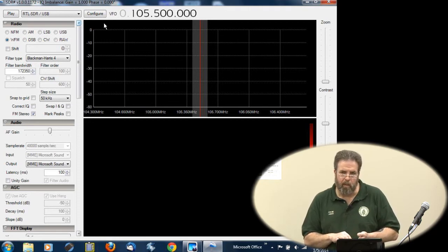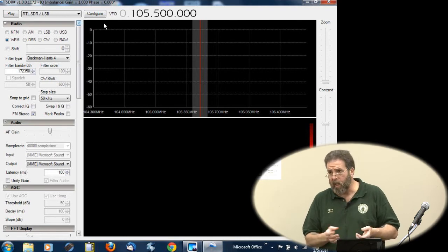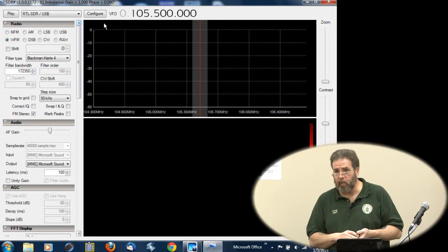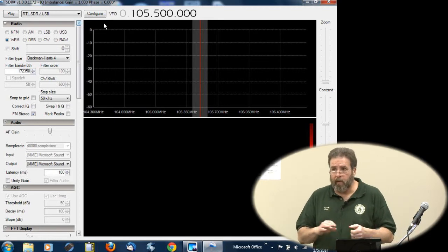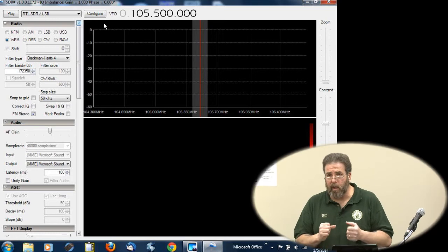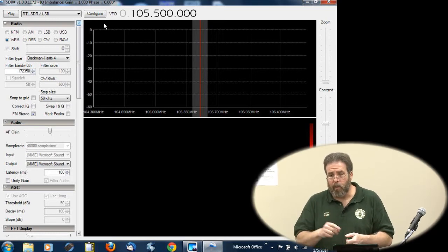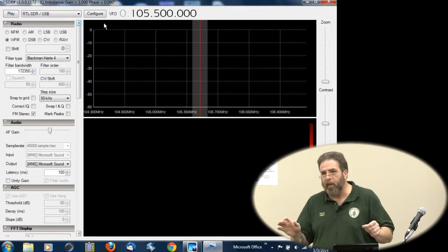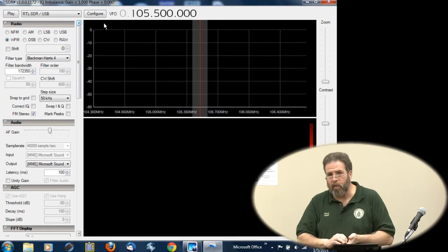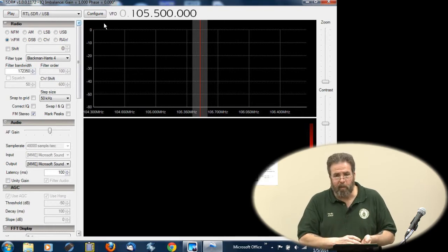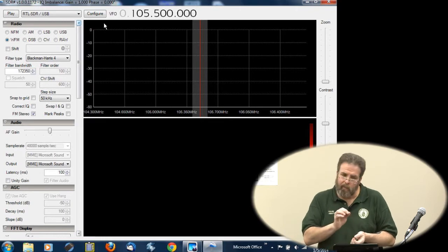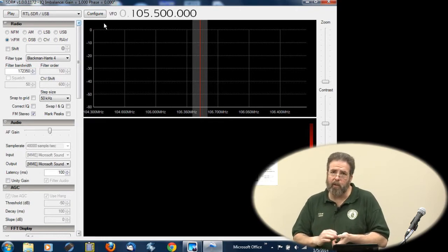I was playing with it a bit yesterday. Like I said, I was listening to guys yesterday. Also, you have to calibrate these. All SDRs have a little bit of calibration you might have to do, and it's really simple. Especially for HF, you just tune in WWV. You let your system warm up for 20 minutes, a half hour, so the oscillator gets nice and hot, and then you tune in WWV in sideband mode or AM mode. Zoom all the way in to WWV's center frequency, the carrier. If you're displaying 15 megahertz and your carrier's off a little, you just crank in a little bit of correction. And usually once you enter the correction and center up that carrier, you never have to touch it again.